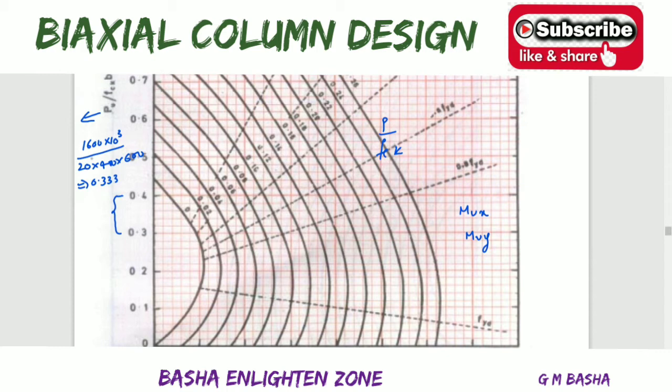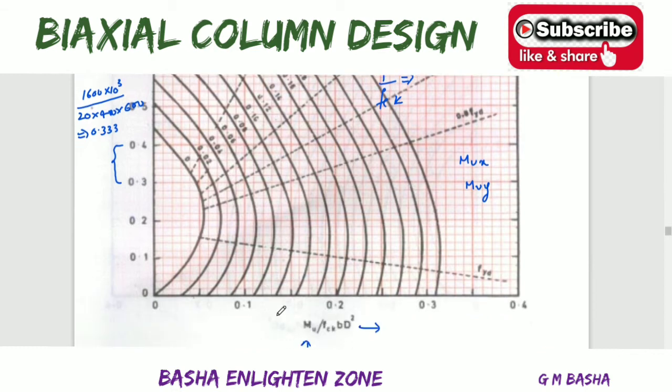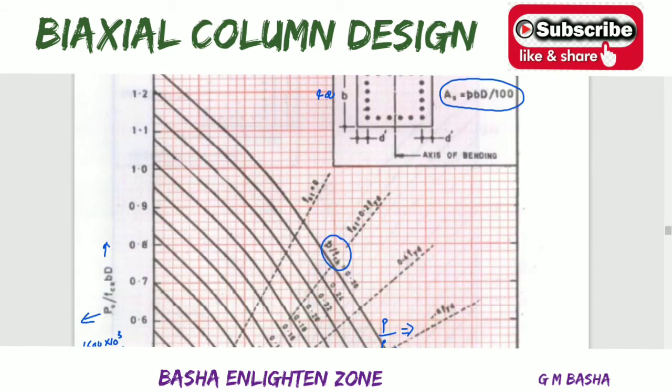That is the first point. And the second point is what I told you. Based on this p by fck, please find out this Mu value. Based on this reinforcement, we have to find this Mu value. If you want to find this p value, there will be p in the formula from the chart. So assume some percentage of the reinforcement, and then based on the provided area of the steel, relate that to the p by fck.